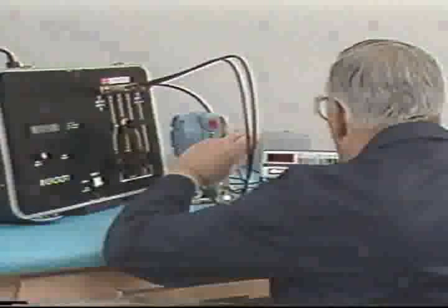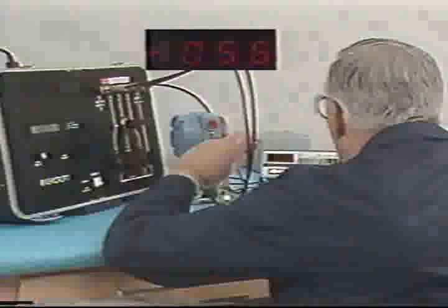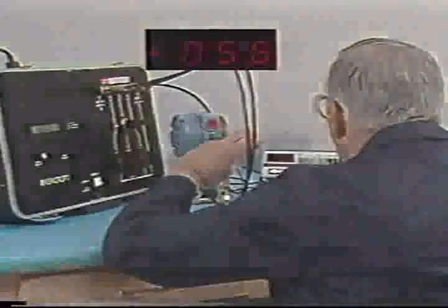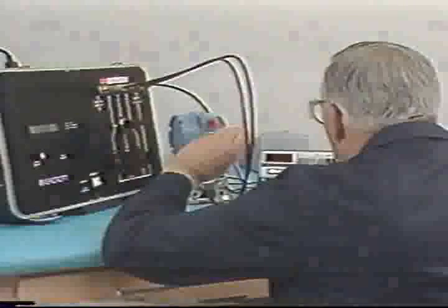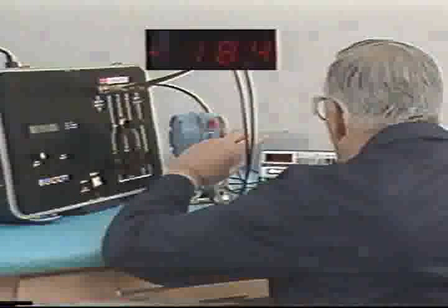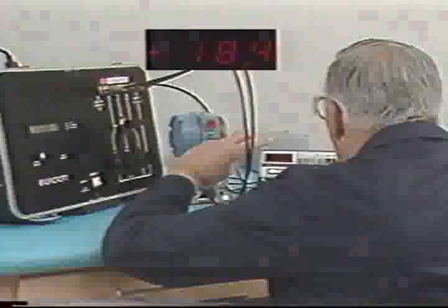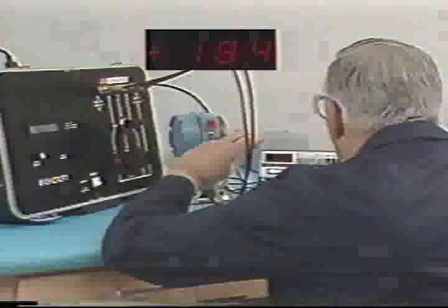The zero should be corrected first. With the input pressure at 10%, adjust zero until the output produced is 10% or 5.6 milliamps. Next, correct the span error, applying 90% input and adjusting the span until 18.4 milliamps is produced. Keep checking the zero and span and adjust as needed until they produce values within specifications. Then, do a final 5-point check to verify the calibration and record the values.